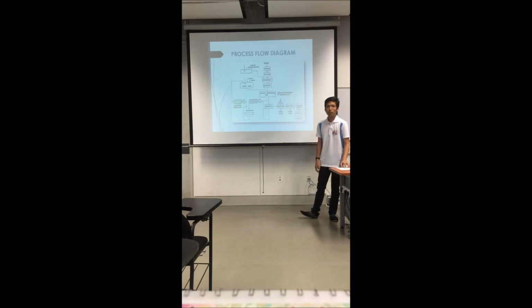As for the major units, we'll start with the sulfiting tank. So, the sulfiting tank is basically a tank in which the sulfitation process takes place. SO2 is introduced to the fruits to prevent microbiological degradation or unwanted color formation, which means the fruit will be preserved better. And the next is the osmotic dehydration tank, which is the heart of the process.